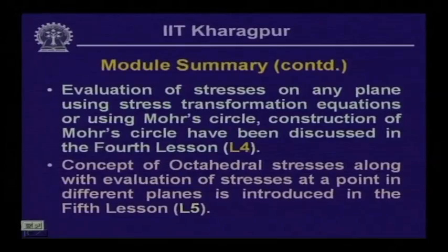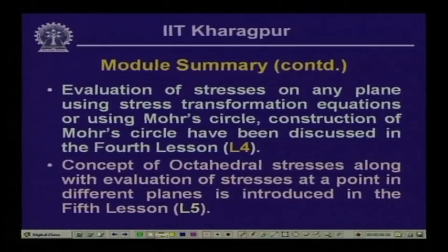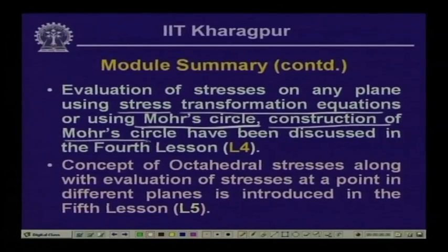In the fourth lesson, we evaluated the stress on any plane using transformation equations. In fact, we have discussed this in this lesson as well, how to evaluate stress at any plane using transformation equations or using the Mohr circle. We have seen these two kinds of problems in today's lesson as well, and in the fourth lesson we discussed in detail how to construct a Mohr circle if we know the stresses at a particular point in a body.